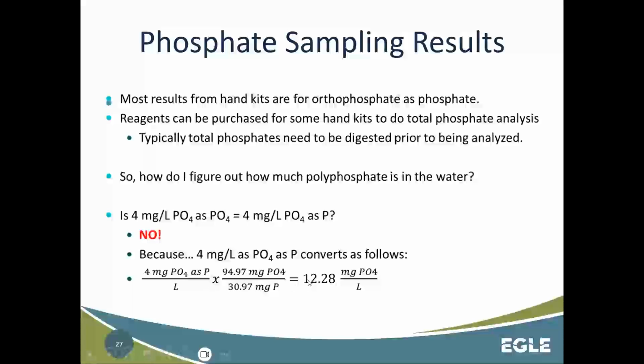You are getting the right values here. You're reporting them to Eagle appropriately. Okay, so you're not overfeeding or underfeeding. So make sure you're getting your units proper, milligrams per liter of PO4 as PO4 or as P or as phosphorus in that regard. Okay.